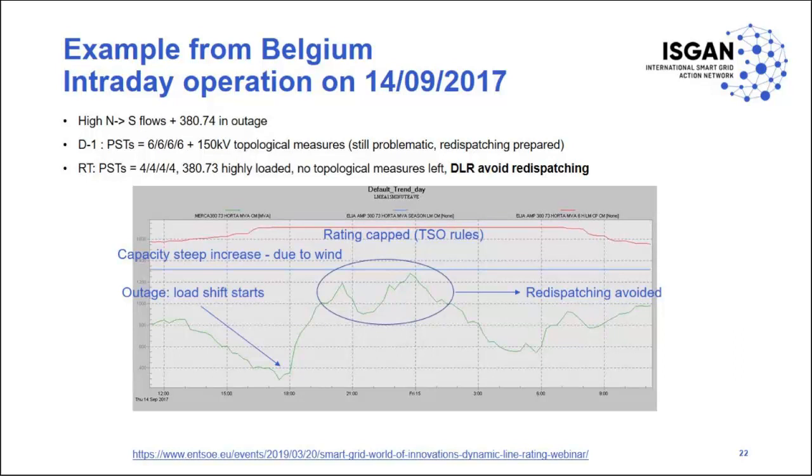So at this point, they prepared to instruct some power plants to redispatch. This means instructing power plants in France to divert from the production schedule and increase their output, while at the same time instructing power plants in the Netherlands to decrease their output. Belgium is limited in terms of power plants in its own territory, especially to counter the expected large north-to-south power flows.